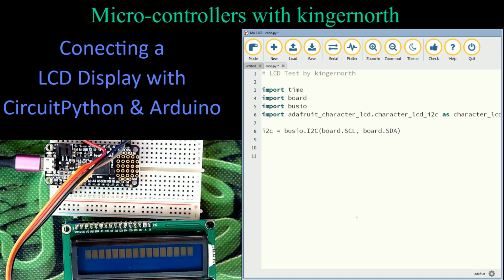Now that we've got pins to talk to, we have to set more parameters for this LCD. This particular LCD that I'm using has 16 characters across by 2 rows. So we're going to have to add those labels in here. I've already got some pre-written text ahead of me, just to make my life easy. In this case, we're going to say there are 16 columns, and then lcd_rows, and we're going to make that equal to 2.